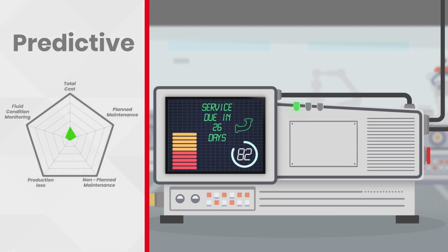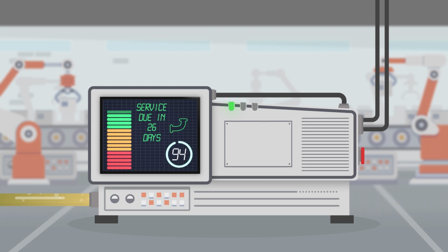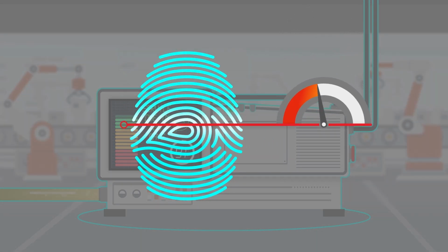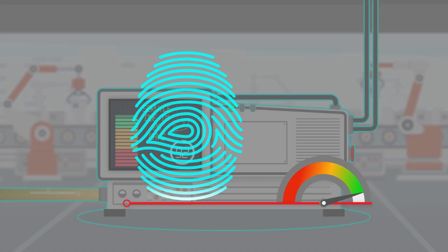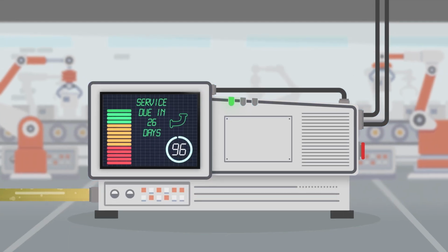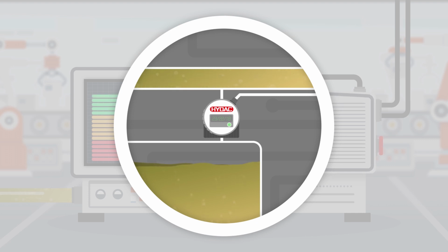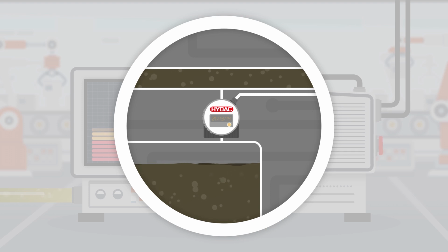over the machinery's lifetime. To allow for a predictive maintenance strategy, monitoring the condition of the operating fluid is of major significance. The condition of the operating fluid is comparable to a fingerprint of the overall condition of the system. By implementing a predictive maintenance strategy, the service life of all critical machine elements can be fully utilized by monitoring any variation from the normal condition early on.